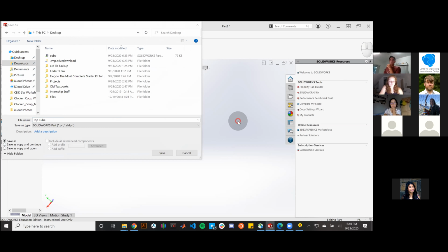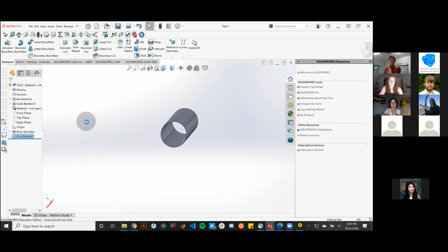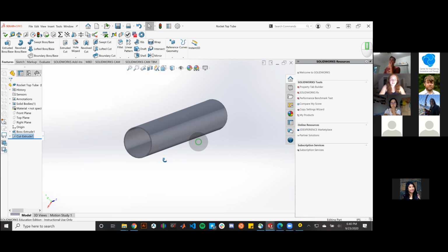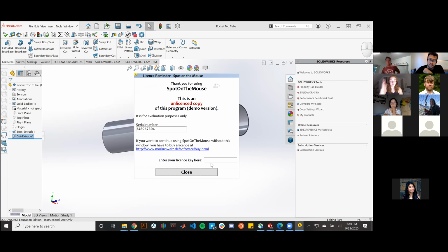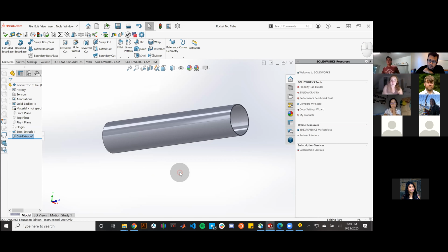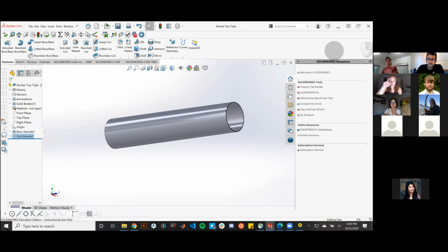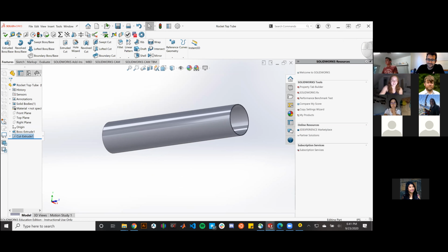Just a note, knowing what folder you're saving it to and paying attention to that is really, really critical when making assemblies. SolidWorks can get really finicky if your files aren't where you say they are or if they're not all in the same spot. So whenever you're working on a project, my top recommendation is to make a folder when you start, put everything in the exact same folder, and don't move it, because moving it can break links. You can move it if you need to, but it might take a little bit of grief. So start organizational skills at the beginning of the project.